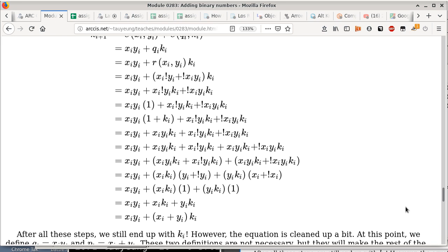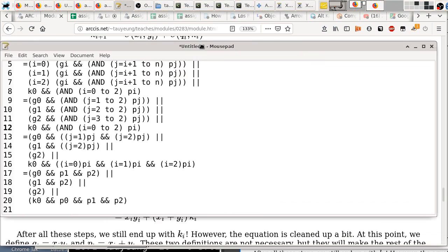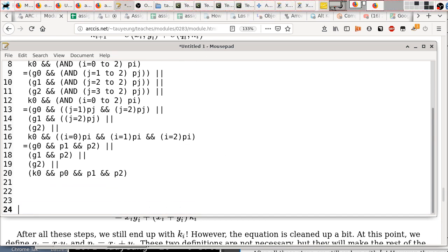Okay, so there's that. So let's work with binary subtraction. I hope you remember when we talked about binary addition, there were 4 cases. And there are also just 4 cases when we talk about binary subtraction. So just like with binary addition, before we talk about binary stuff, let's talk about base 10 first. What is 3 minus 7? -4. 3 minus 7 can be seen as -4, but it can also be seen as a 6 with a borrow.